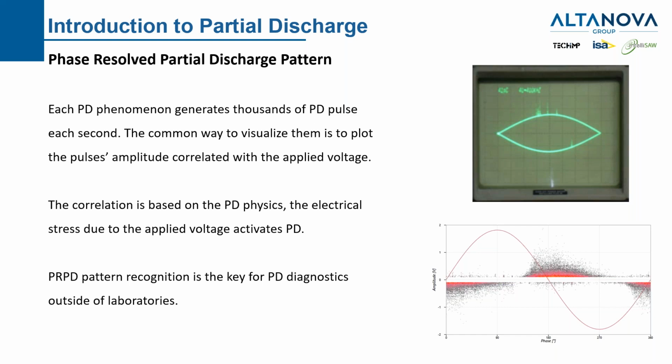The voltage gives us partial discharge. If we don't have voltage, we don't have partial discharge. If the voltage goes up and down as in a sine wave, we will have a pattern with some features and characteristics that we can recognize in several assets and experiences.